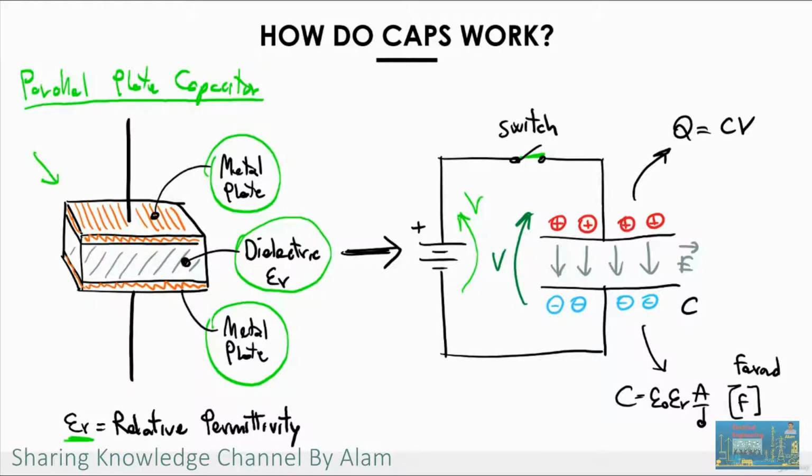As we discussed before, the capacitor is made of two parallel plates, which are made of metallic material. You can think as if they are made with the same type of material as the wire, so just like a strange looking wire. But in the middle, there is a material that is an insulator. So it's kind of intuitive to think that maybe something will happen just the instant after you close the switch. There will be some current, some readjustment of charge and voltage. But then eventually, the current through the circuit has to be zero.